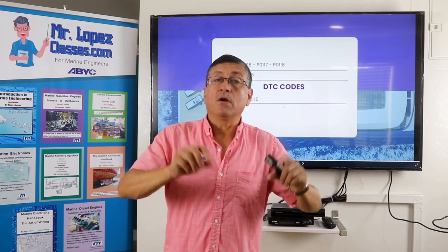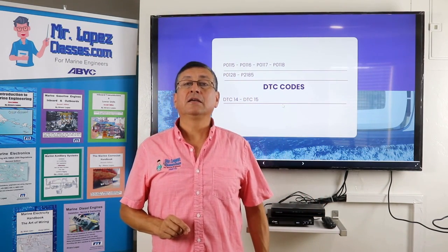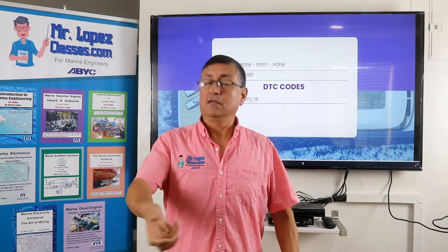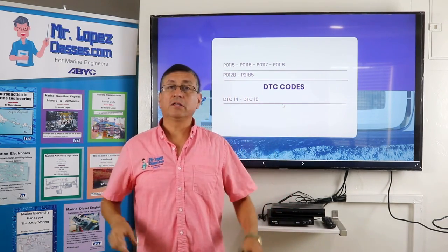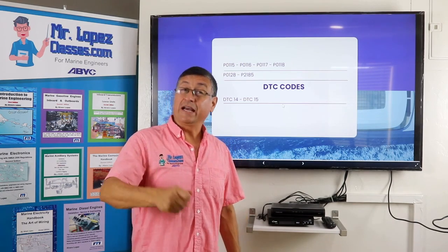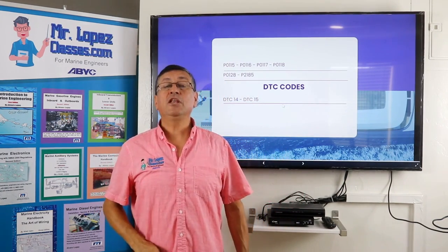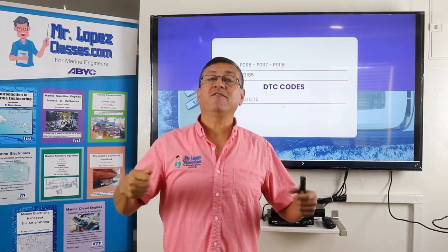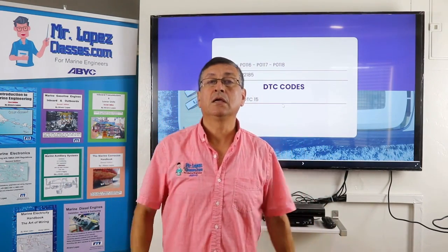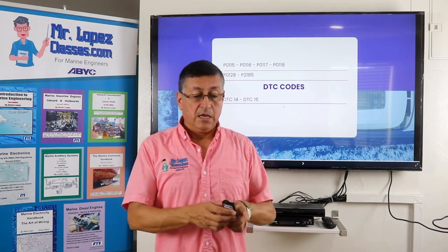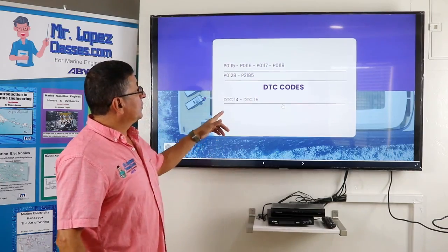If you fix the problem, after that, you can clean the codes and verify. Turn off the engine for more than 1 minute, disconnect the positive of the battery for 1 minute, put the positive back and verify if the code stays again. That's the procedure. It's simple. Alright? We are going to check right now, those are the codes.